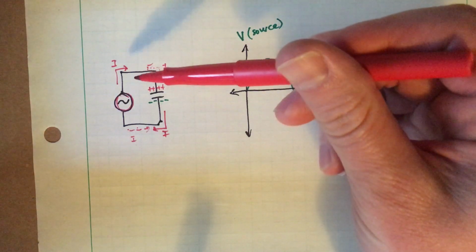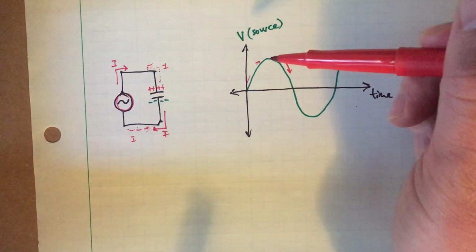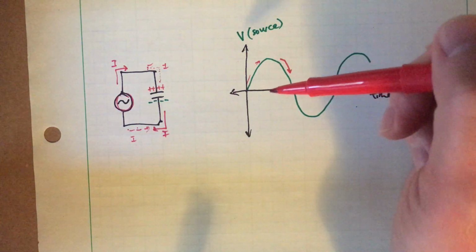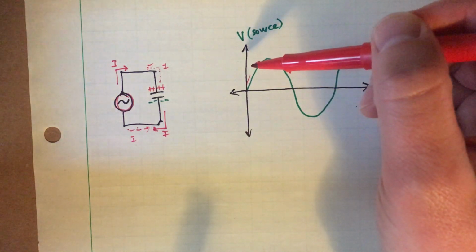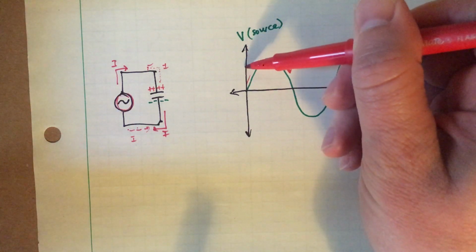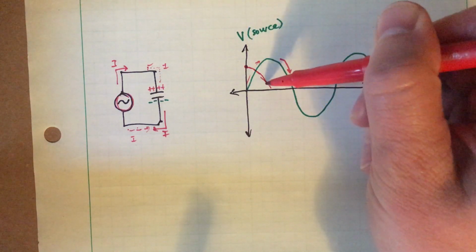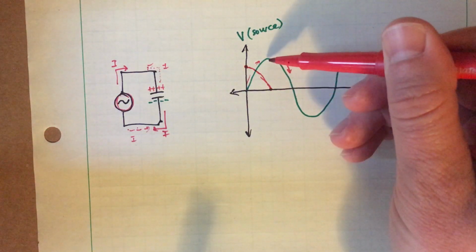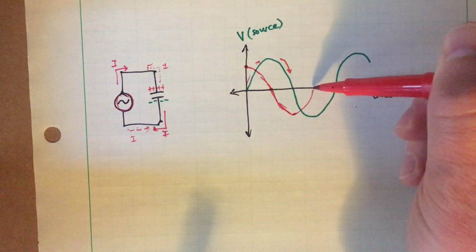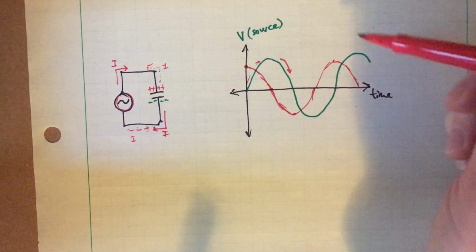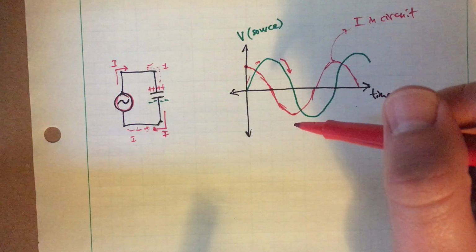And what that results in the circuit is a shift in the moment in time between when the source voltage is at a maximum and when the current flowing in the circuit is actually at a maximum, right? So if you were to connect the AC source and wait until it equilibrated and was in a steady state, what you would actually see is the following, which is kind of bananas. You get a peak in the current when the source voltage is 0, and the current is 0 when the source voltage is at a peak, and then it comes down here and is a peak, well, a trough, in the other direction. Okay, and then again a 0 when this is at a trough, and then up here, and then back down here. And this is your current in the circuit. This is weird. All right.